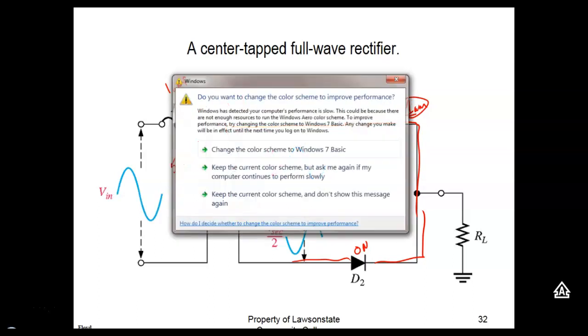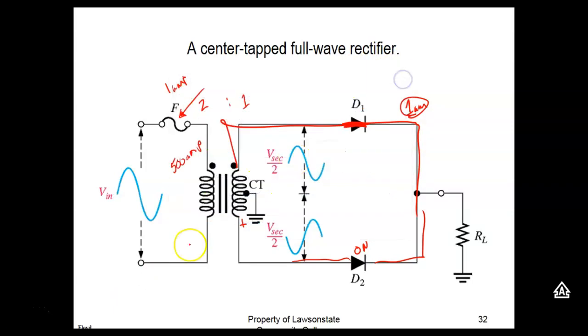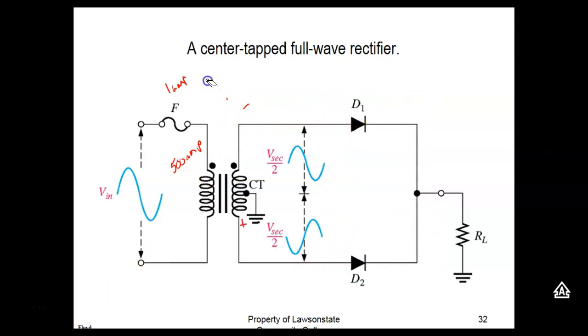So if we get an open in a full wave rectifier, what's going to happen is it's going to convert it into half wave. So that means if I'm not filtering it, my output voltage will drop down to 1/2 of what I expect. And that's troubleshooting power supplies, guys: not putting meters in there to see what's there, but putting your meter there to verify what you expect.